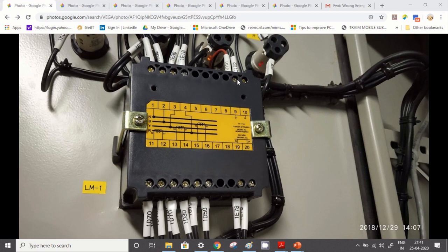Wherever there is an issue, like few meters are in the gigawatt hour range, in that case it always moves every 10,000 megawatt hours. So for example, if your energy meter shows 68.1 gigawatt hour on the meter display, in the Everest you will see only 68 gigawatt hour. 68 into 10 raised to 6, that is the kWh there, but that kWh will remain the same on day 1, day 2, day 3, day 4, because the value will change in the Everest only when 10,000 units get consumed. So for example, it is 68.1, in Everest it will show 68.0.